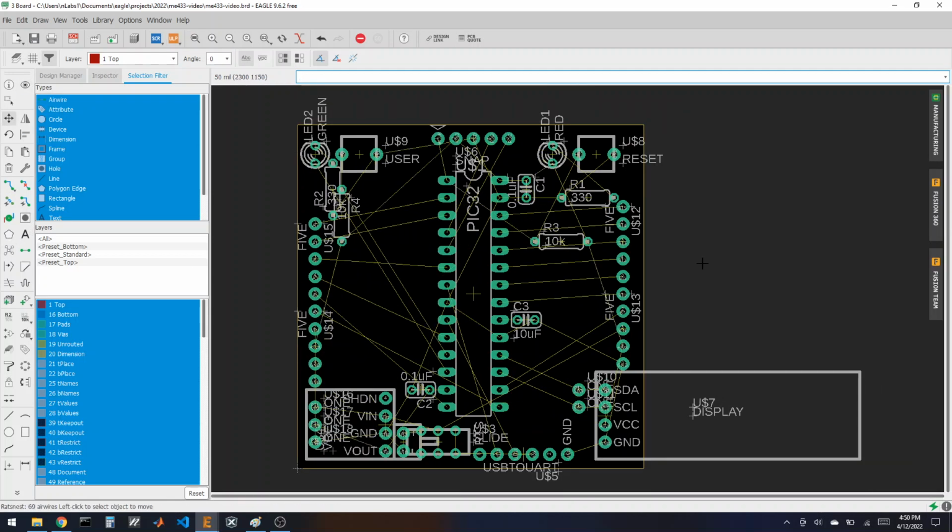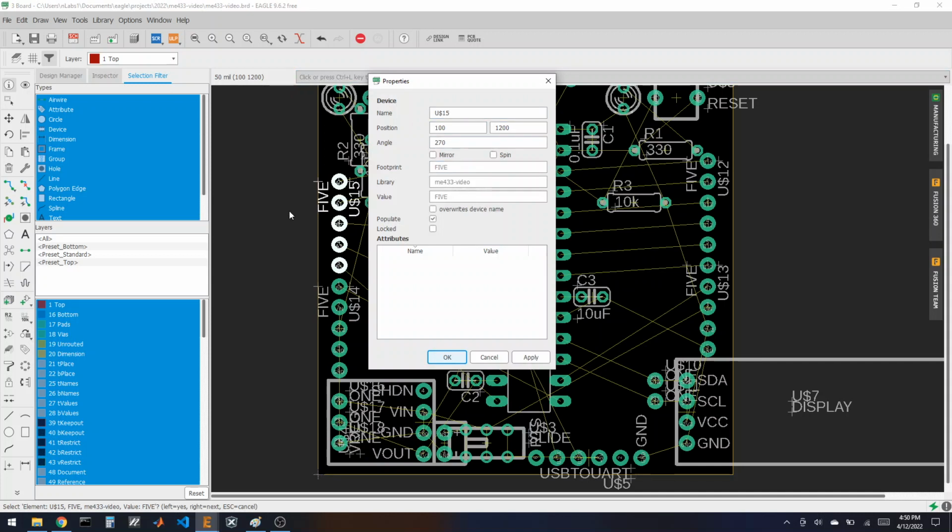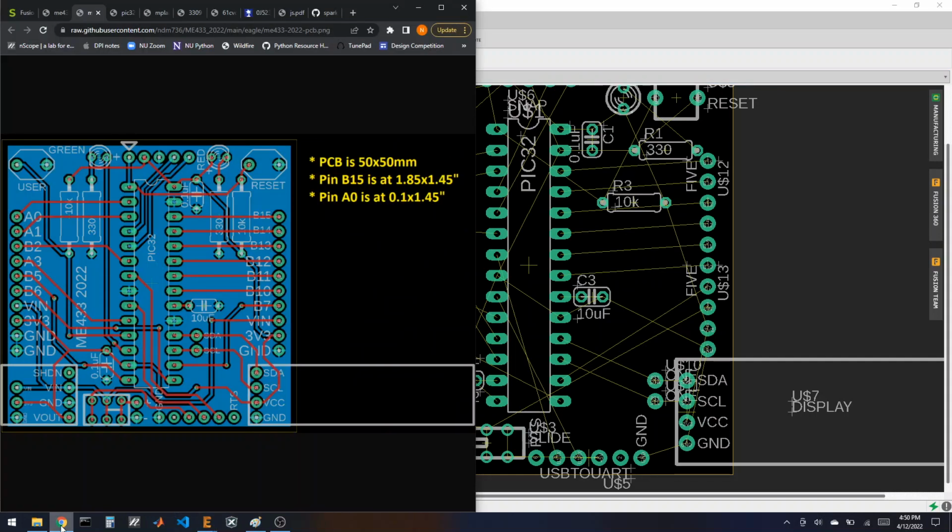Now maybe a little bit more organization. First, let's figure out how to get my header pins in the right position. So the downside of putting the center pin as the origin for this connector instead of the top pin is that I need to make sure the top pin's at a certain location, but it's 0.1 lower than it's supposed to be. 0.2.